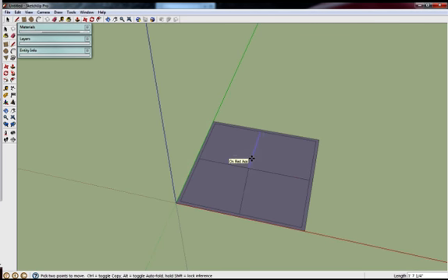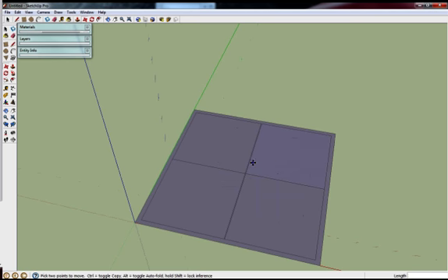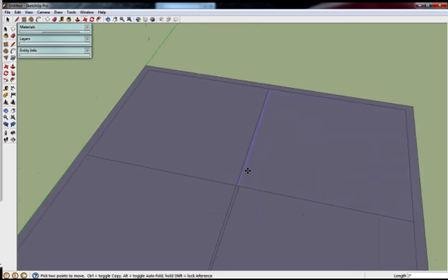Let's give the interior wall some thickness. Grab the Move tool, the M key, and select a wall. You'll notice that it's moving the line around. Hit the Control key. You'll see a little plus symbol, and you see a copy of the line moving around. Using the inference, you can place the line 2 inches over in the red direction. Go ahead. Do the same thing again in the opposite direction. Now you have 3 lines. Erase the middle line with the eraser tool, the E key, and you have a 4-inch wall thickness.